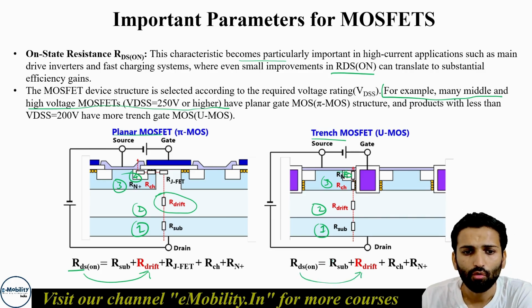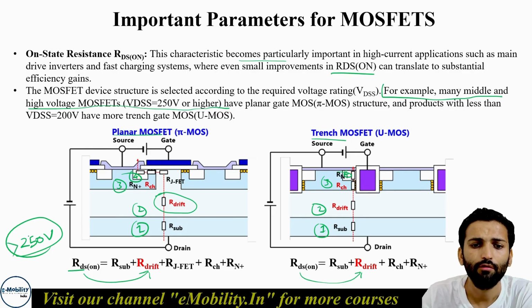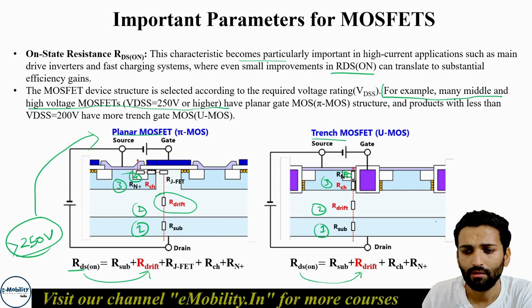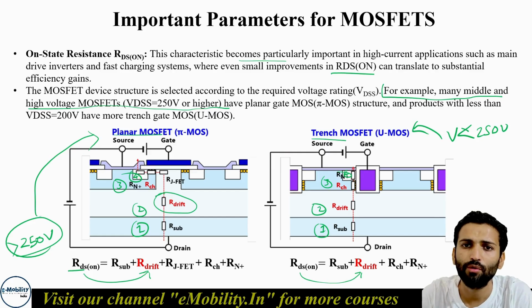drift. So for any application having a voltage rating of 250 or higher, we'll be using planar MOSFET, and anything with voltage less than 250 volt, we'll be using trench MOSFET, because the resistance offered by planar MOSFET in higher voltage rating is lower, and by the trench MOSFET in lower voltage rating is lower.